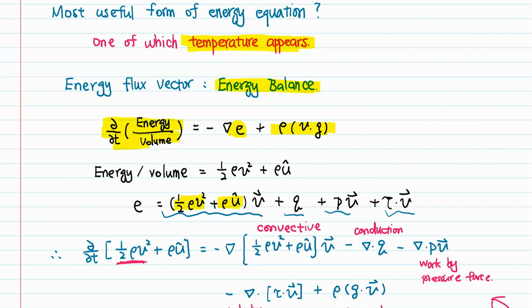So what we're dealing with here is basically just trying to expand all terms to come to our most generic form. So we have the accumulation of energy, which is the sum of the mechanical and internal energy, equals the energy obtained by convection, by conduction, and also work associated with pressure forces, with viscous forces, and external forces.